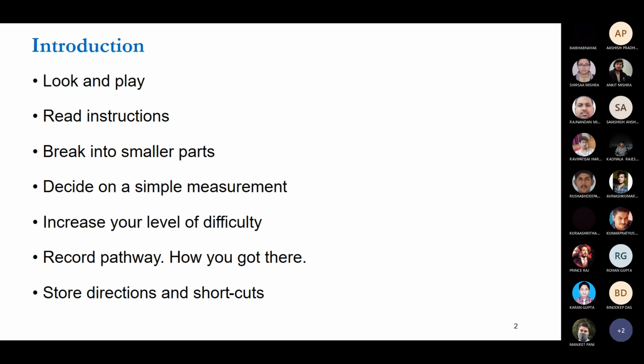There is a scale that looks like a pot, and you can change its position. Varying it changes the volts per division, the unit per division. If you change the unit per division, the range varies automatically.